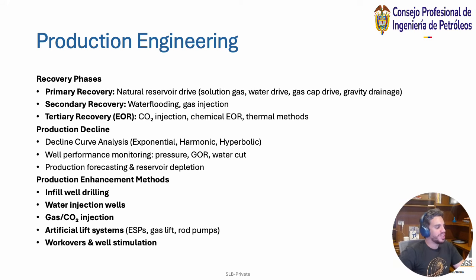When you think about primary, secondary, tertiary, most people think that, okay, I'll take some in primary, some in secondary, and all of it in tertiary. And that's just not the case. The current technology in the 20th century is that primary recovery was like 10 to 12%. Secondary recovery took you to like 20, 24% if you were lucky, and tertiary recovery took you to 30 to 40%. And then with fracturing and the advancements of technology, you were reaching higher, like 50 or whatever percent.